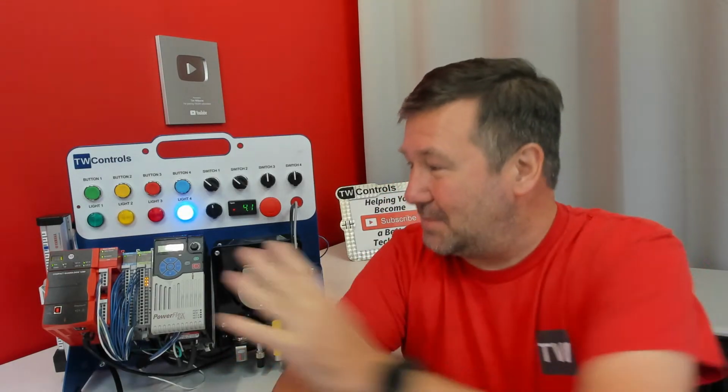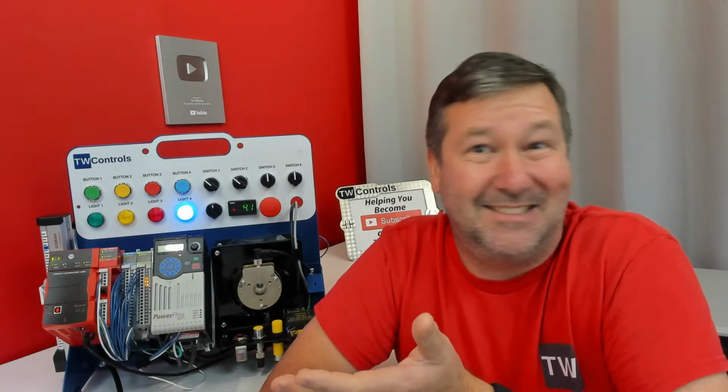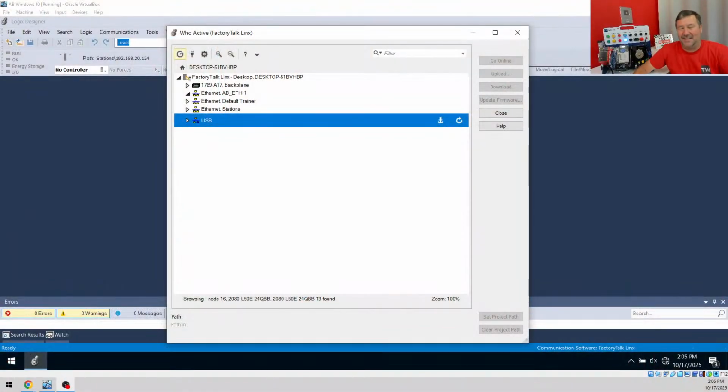So while USB is cool, you actually don't use it that often in the field. For one, USB is only good for 6 feet. And it's rare you can actually get within 6 foot of a PLC. So let's talk through some of the Ethernet things.